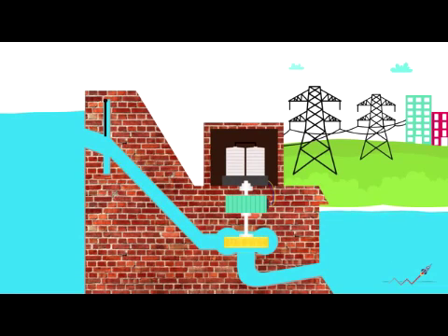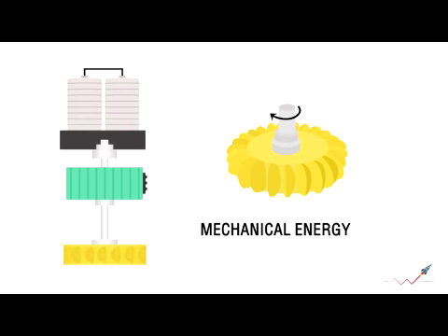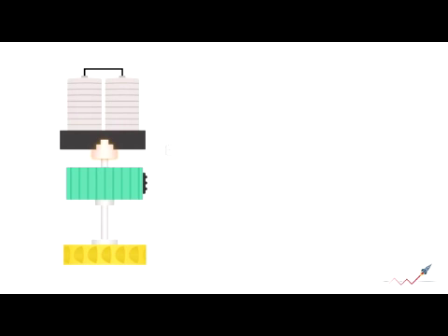It is designed in such a way that the gravitational force pulls the water down to the turbine, which produces kinetic energy. Turbines consist of large fan blades and a spindle. The spindle rotates when the water strikes the blades, thus converting kinetic energy to mechanical energy. On the top, there's an exciter, which gets small DC power. Below the exciter is the generator.